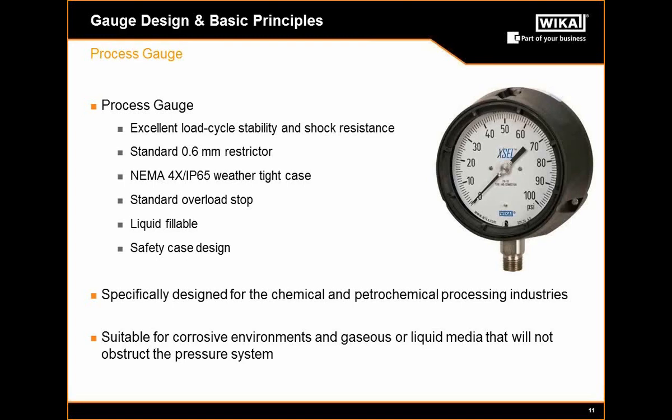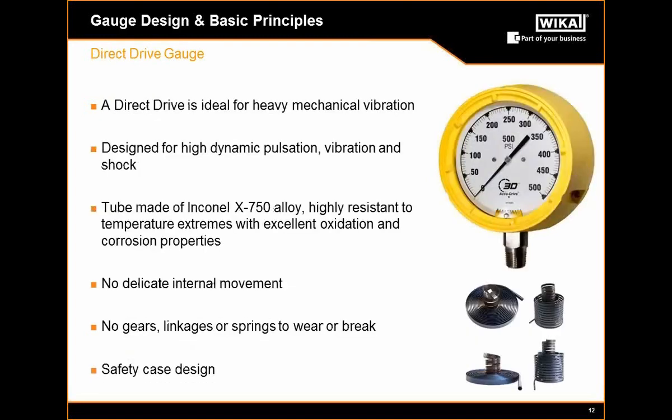A newer technology that's been born in the last few years is the direct drive gauge. It's ideal for heavy mechanical vibration, high dynamic pulsation, and shock. Inside of the gauge, in lieu of having a Bourdon tube with the movement and internal moving parts, it's got, as you see in the bottom right, a coil, what we call the helicoil, that's made out of Inconel X750. It's highly resistant to temperature extremes.